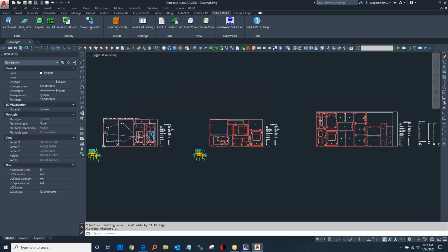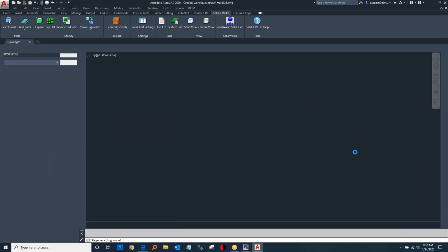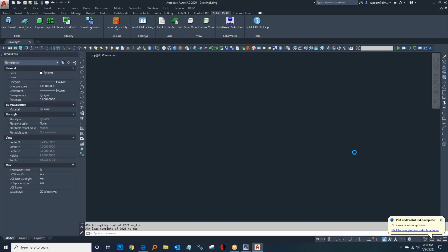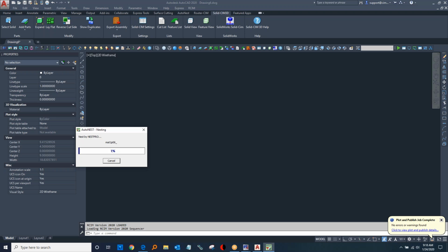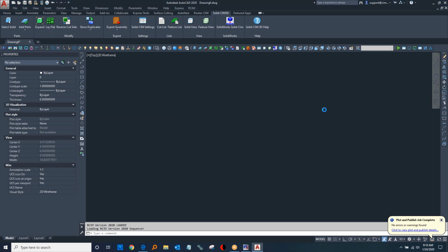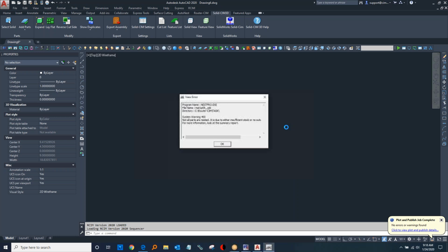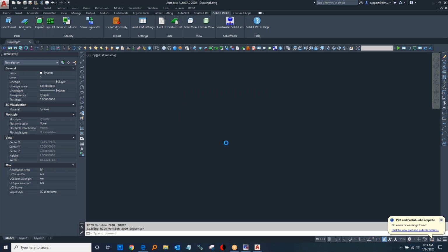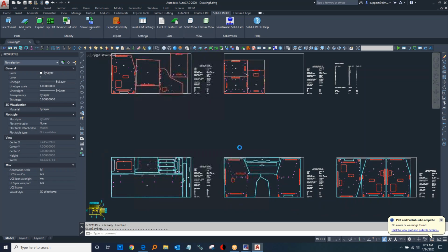We also got parts inside of parts nesting. So inside this opening of these parts, other parts fit inside there. I'm also using the stay down nesting so the tool stays down and connects from part to part without lifting up. That saves cycle time. You could save up to 20% on your cycle time every day. If you have a lot of parts in your nests, instead of the tool lifting up and rapiding from one part to the next, it'll keep the tool down and connect from one piece to the other without lifting up. That can help when cutting melamines. You won't get a lot of chip out because you're only entering and exiting the material one time.